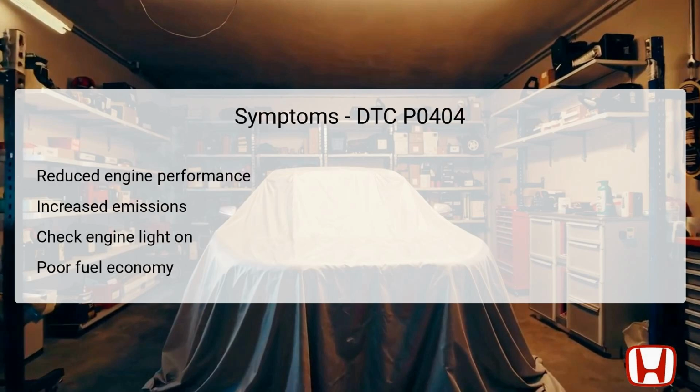When the DTC P0404 is triggered, certain symptoms may manifest, indicating underlying issues that need to be addressed. Drivers may notice reduced engine performance due to improper air-fuel mixture resulting from a malfunctioning EGR system. The increased emissions, both in terms of hydrocarbons and nitrogen oxides, are not just a concern for compliance, but could also lead to the vehicle failing emissions testing.